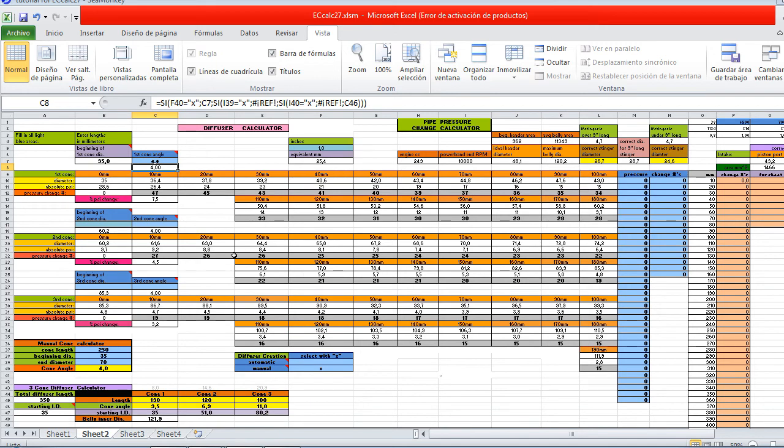And because the second section is being used by the first cone, I'm going to use the third section for the second cone. So if the end diameter of the first cone is 70, the beginning diameter of the second cone is also 70. So we'll put 70 right here. And I don't know the angle, so I'm going to figure it out here. That's 100 for the second. Beginning diameter of 70, end diameter of the belly. That says it's 14 degrees. So I'd enter 14 right here.